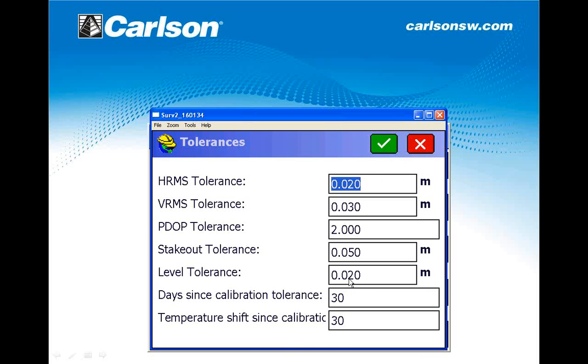I tell you, with a 2 meter pole, 2 centimeters is something realistic, I would say. Below 2 centimeters, it's really hard to make it match and keep it vertical by using a hand, okay? Unless you're using a bipod or a tripod or something like that. Anyway, let's say 2 centimeters for this case.